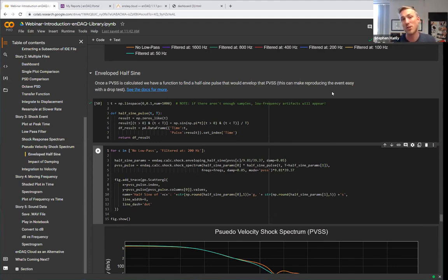Typically you're doing shock testing because you want to inform some design decisions. So you'll want to know, okay, I have the shock event. It's really being amplified if I had a natural frequency in my system at 50 Hertz. So I have to avoid that, or I have to add in an isolator. You can't get any of that insight by just looking at peak-to-peak acceleration in the time domain. That's impacted by sampling rate.